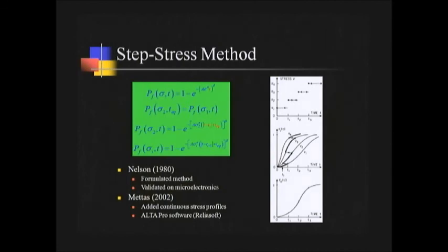But he has developed an equation for that, his cumulative damage model, where you figure out at the point in time where you step the specimen up to the next stress level, you figure out how much time has elapsed, and according to the inverse power law, how much damage should have accumulated. And then you calculate the equivalent time to accumulate the same amount of damage. It will be a shorter time at a higher stress level.